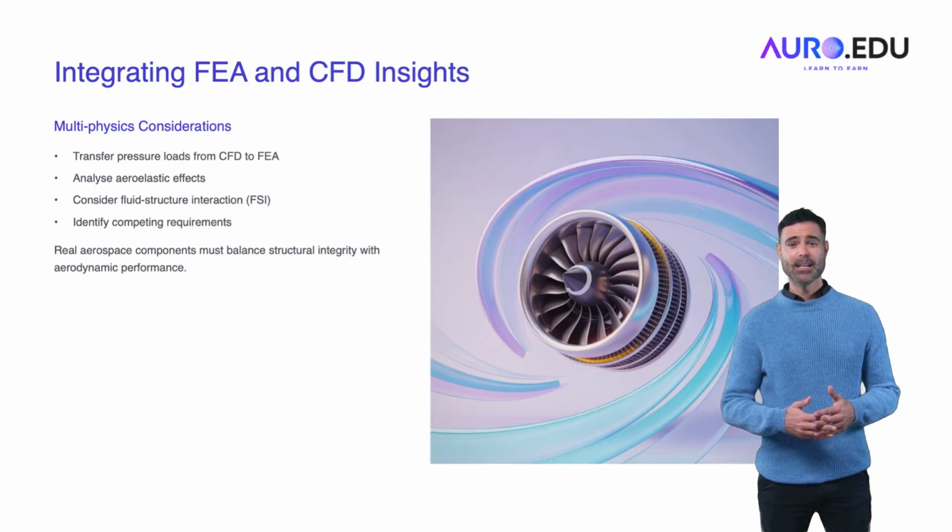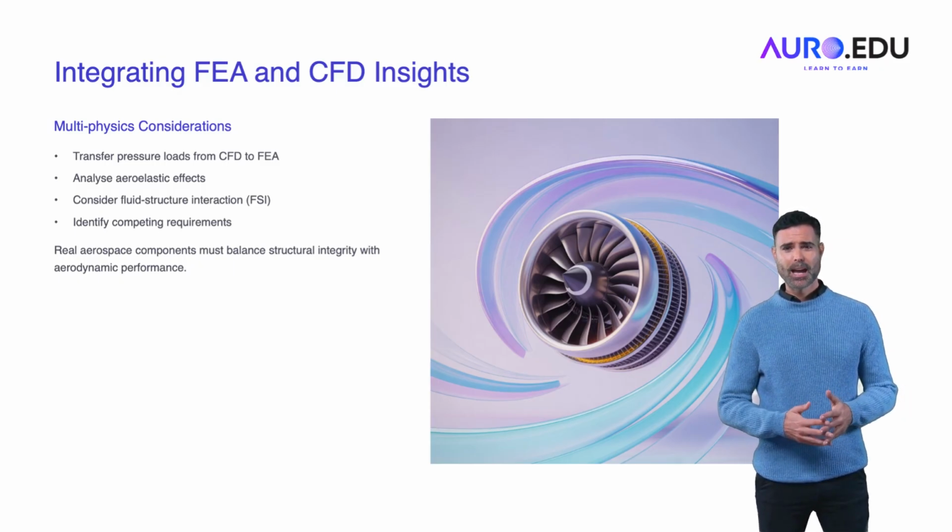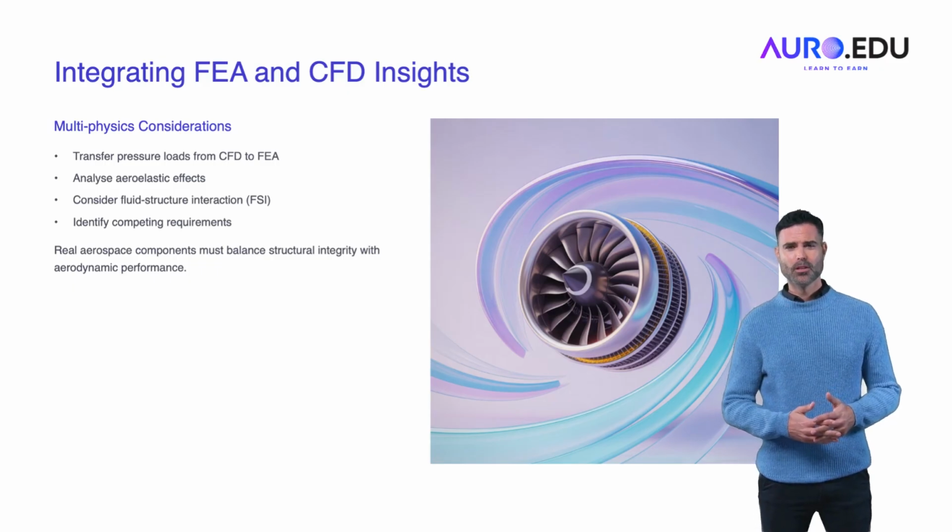Integrating FEA and CFD insights. Advanced designs often require integrating FEA and CFD. For example, use pressure from CFD as input loads in FEA. Explore aeroelastic effects and even fluid structure interaction. This multi-physics mindset is how modern aerospace systems are engineered. Your design must perform well structurally and aerodynamically.